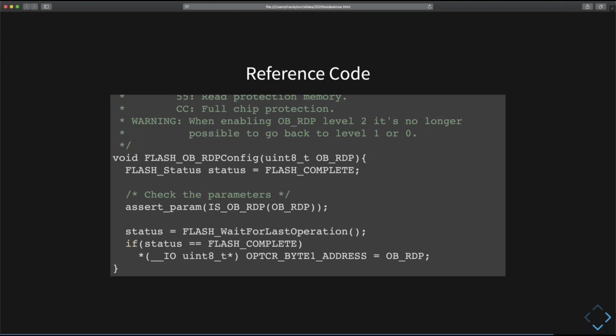To do that, I looked at the manufacturer's reference design, and they provided this example function, which was used exactly with no modification by the radio vendor. It was statically linked into the firmware image. So I could look at what assembly code was generated by compiling this, and then I could search for everything similar. And by searching, I was able to find the correct function in very little time.